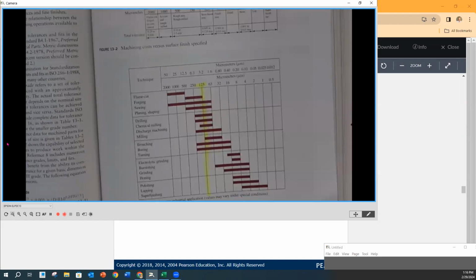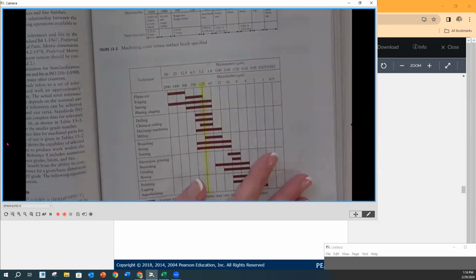Other than that, for seals and such, if you look at an O-ring catalog, like the Parker catalog, they'll have surface finish requirements for sealing applications. Something like this is more custom, where you probably want to look at something else that was designed similarly in the industry, or run your finger across it and do some tests. But I think if you mill or turn something like that on a lathe, it's probably going to be good enough for what you're doing.